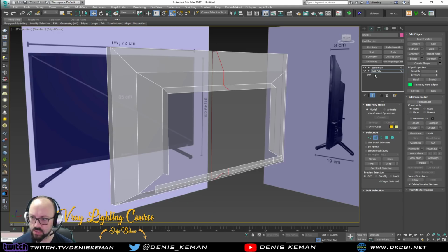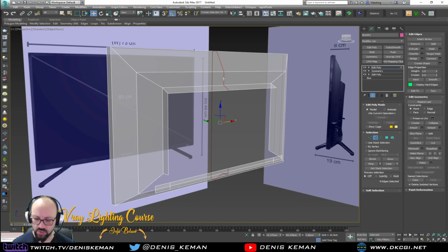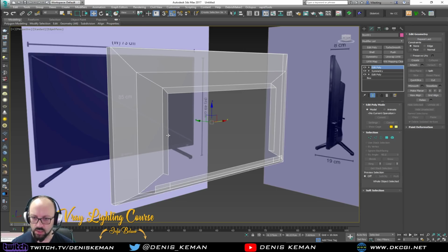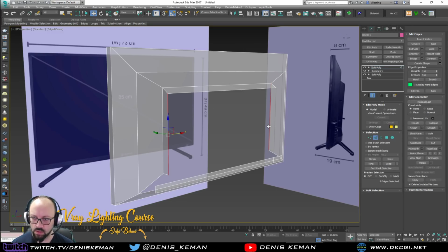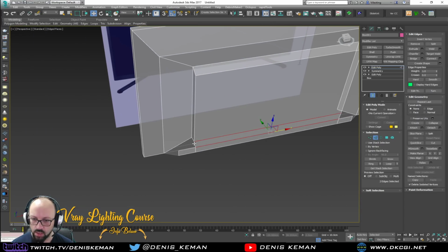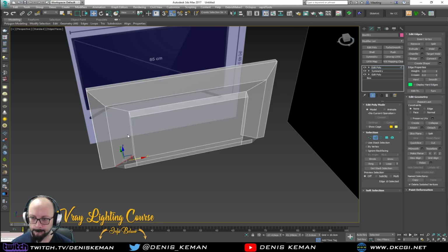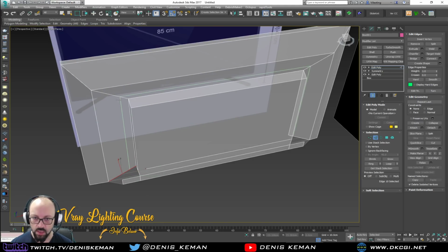Alright, so I guess on top of the symmetry now I can remove the centerpiece, select this edge, nope, this one and this one, bridge it together. This one and this one will be bridged together, and this is gonna be the flat one. So just add in one edge in there.